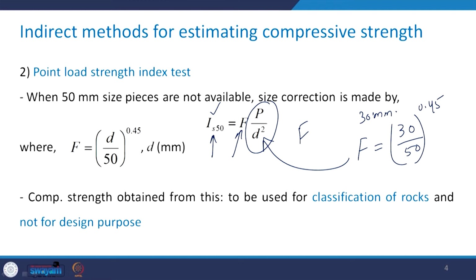Please keep in mind that the compressive strength that we obtained from point load strength index test should not be used for the design purpose.